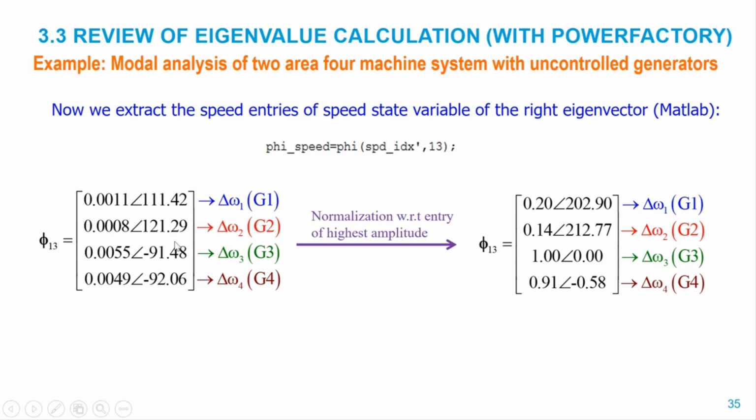The information here to the left was obtained by performing eigenvalue calculations with the linearized model of the system, whereas in the case of Prony, we are extracting the information from a fitted series of weighted exponential functions. So it's not possible for these two to match exactly. In the second case, we are getting information just from a piece of signal, whereas in the first, we are getting information from the whole model that has been linearized.